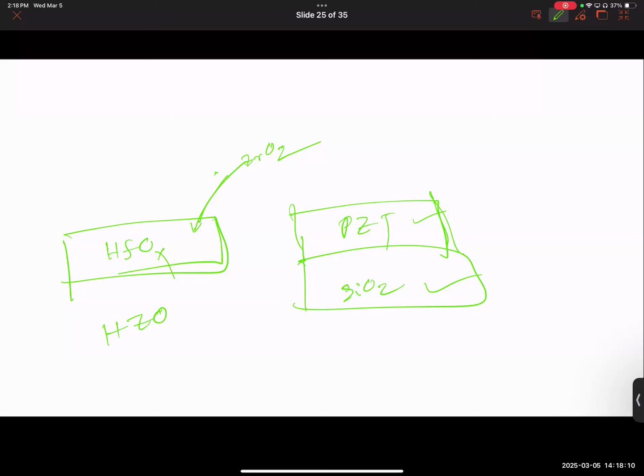Now, you already have hafnium oxide there in the device. You just make a top layer. Instead of hafnium oxide, you can make it hafnium zirconium oxide. And there you go. You have a ferroelectric transistor. The super elegant fabrication methodology. That's why people are so excited. Does that make sense, folks? Okay. Everybody loves, especially industry loves simplicity. Like if it is easy to make, we will go for it. There are less things that can break.